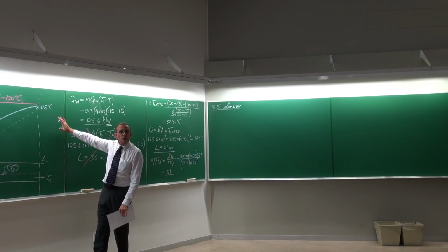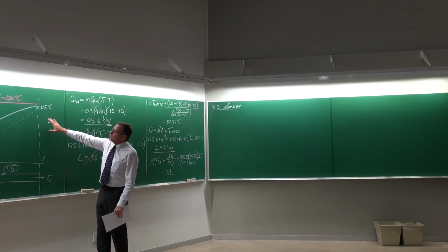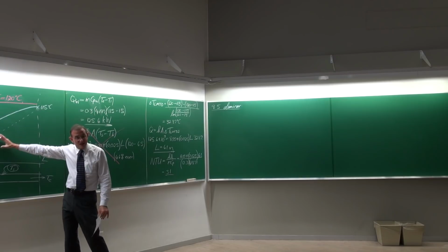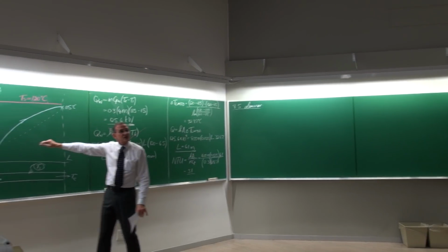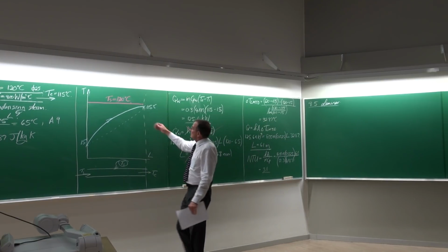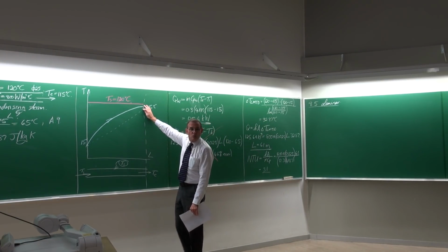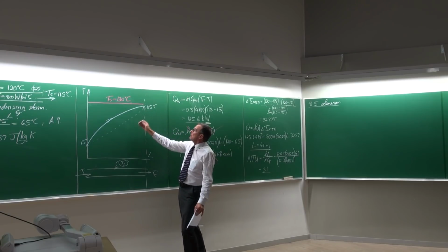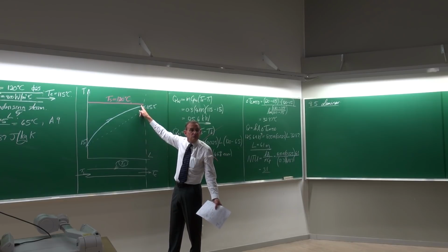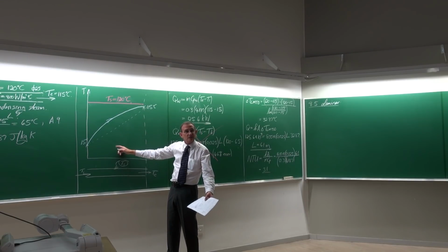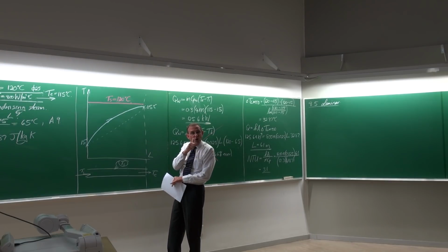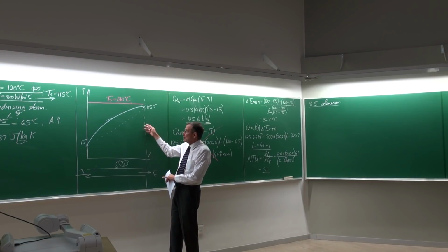We're going to do it later on quite a lot. So in this case, you were spoiled by the fact that you were given the outlet temperature and the heat transfer coefficient. You're going to see that is in most cases exactly what you do not have. So therefore, if you don't have the outlet temperature, you can do one of two things. You can say, well, I'm going to take the average between 15 and 120 as my bulk and get the properties there. Or I know my heat exchanger is not so effective. You know, I hope to get to an outlet temperature of 50 or 60.